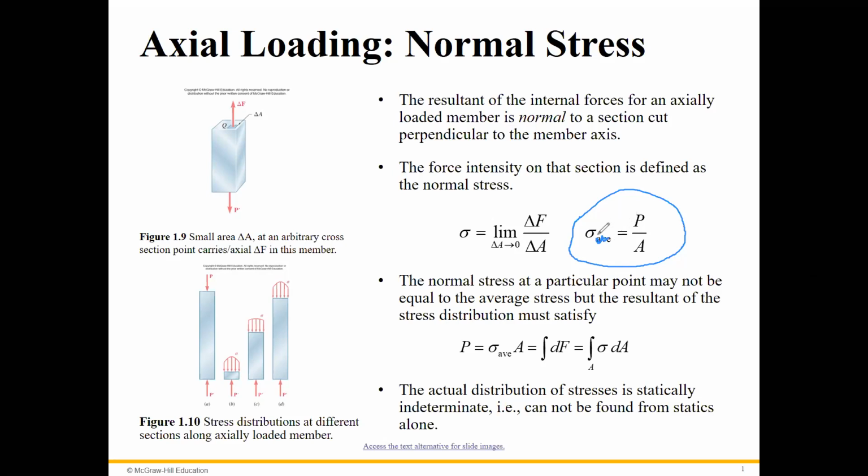If the element is steel, then the stress for the steel would be, for example, 100 megapascal, the maximum one. Once we measure the stress, if our stress is less than the allowable stress, we can say our element is good, is safe. But if the stress is greater than the allowable stress, then that's a problem. Then maybe it's not safe.